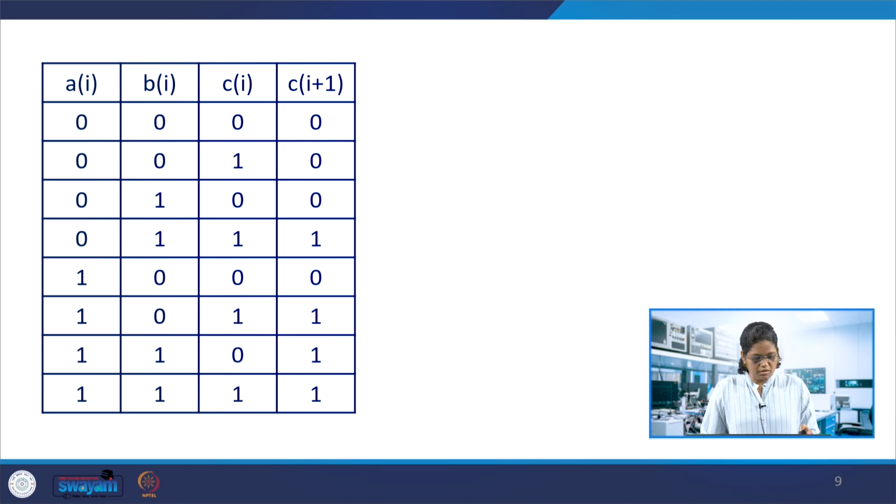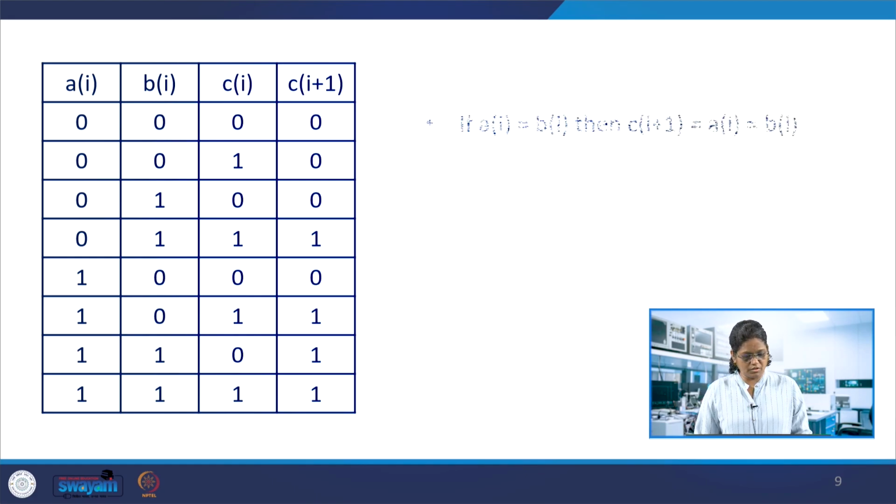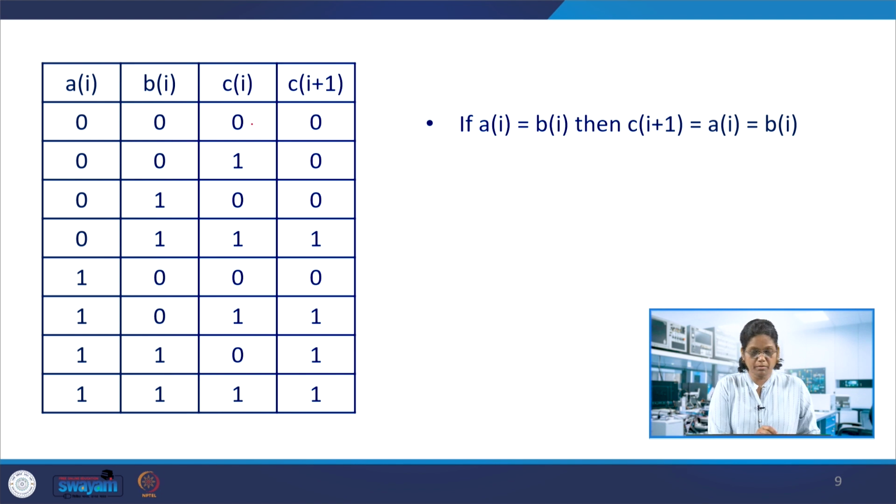So the lookup table, which we used in the previous lecture, the mux structure. We have reduced this to the mux structure, in which the 1 bit full adder, if you recall, has inputs 0 0 and the carry, the other input is 0, and the next carry is Ci plus 1.